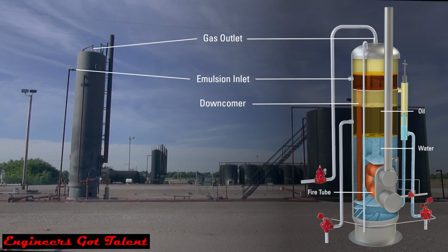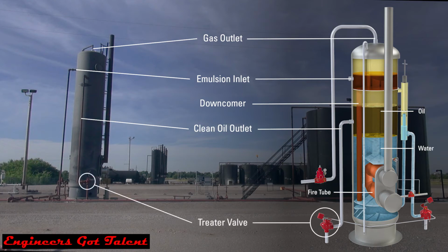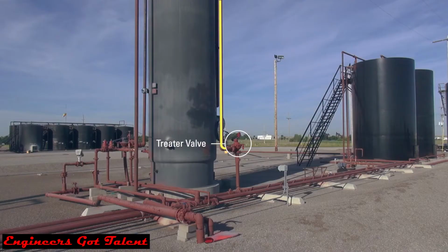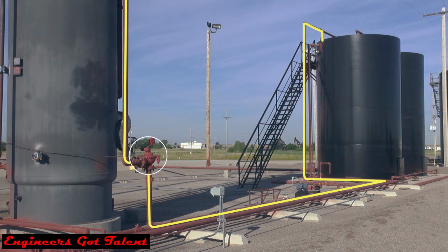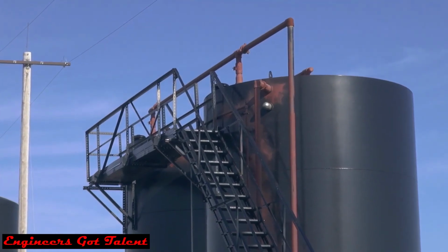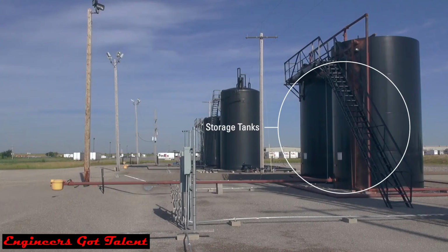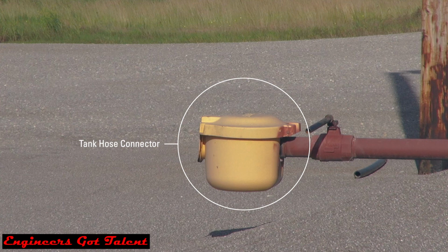As it reaches a set point, oil spills over, comes down the downcomer pipe, and then you'll see another Kimray valve. The treater valve only controls the liquid in the downcomer pipe. It does not control the liquid inside the vessel. As the height in the downcomer pipe meets its desired level, the valve will come open, the liquid will leave the valve, go down the pipe, and into its final destination as crude oil into the storage tank, where the midstream company purchases crude oil from the producer and then it is taken to a refinery for further processing.